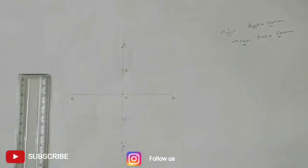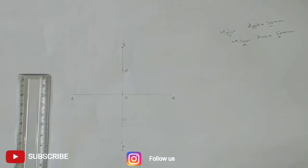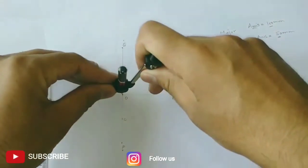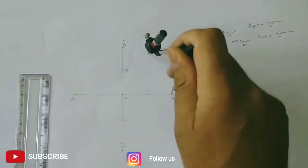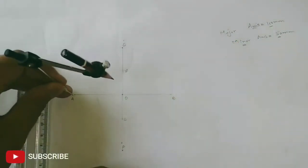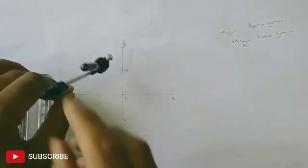Alright. Next, you need to divide this circle whose diameter is equal to AB into 12 equal parts. So I will again open the compass equal to OB, place it at point B and draw an arc in this direction and in this direction, intersecting my circle. Then I'll switch to point A and draw an arc in this direction and in this direction.